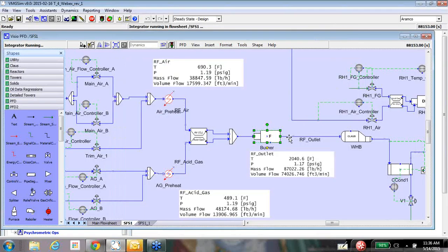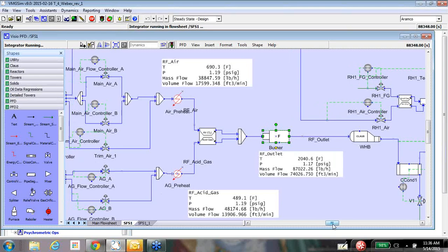For example, some clients have a maximum velocity that should be in piping at any stage, X amount, or the condenser has a maximum velocity of Y amount, or the gross overlay velocity throughout the condenser should not reach more than that. So all those parameters are designed for those guidelines. We need to check, for the different scenarios we are running, whether those will match or not. And that's when this model is really helpful.